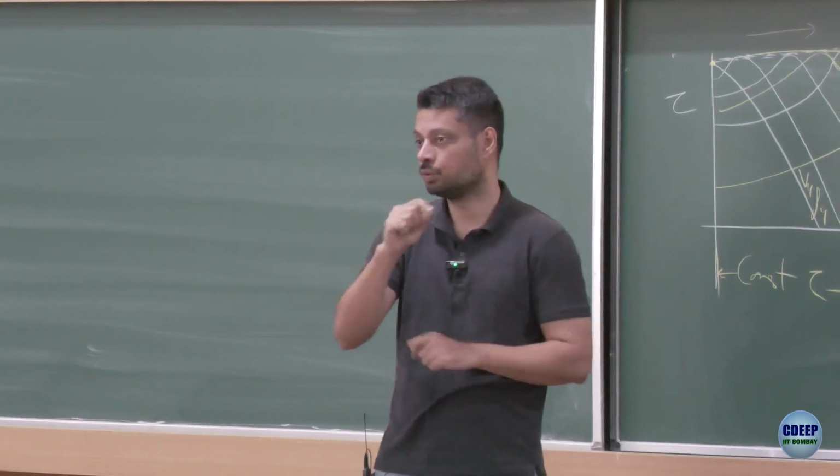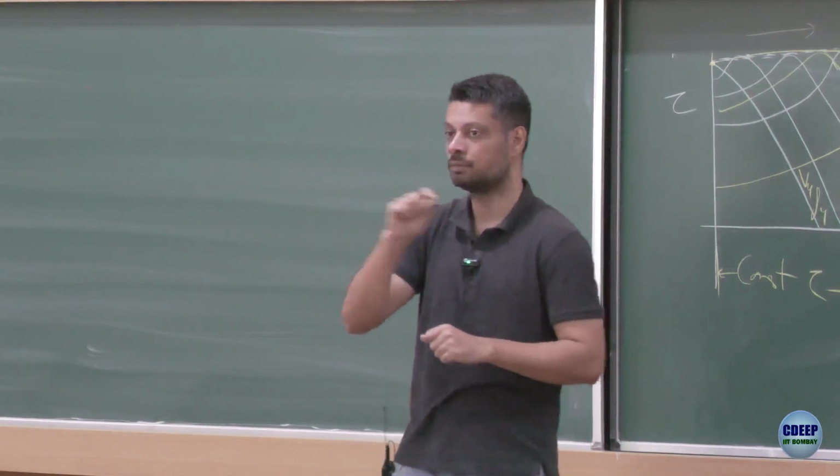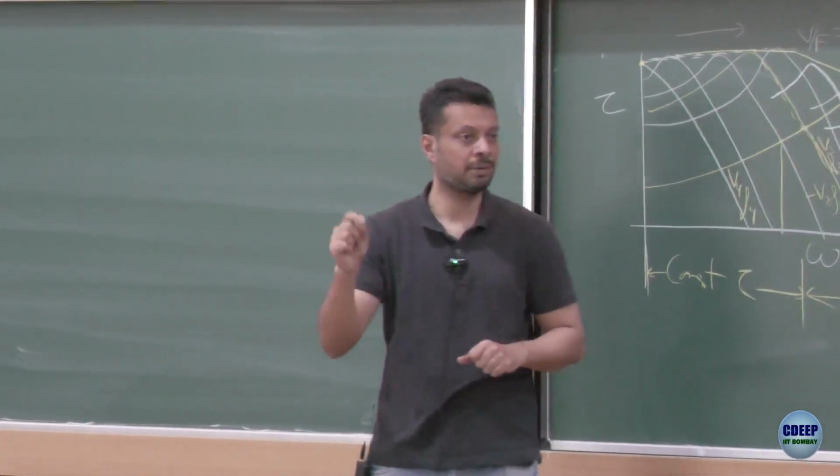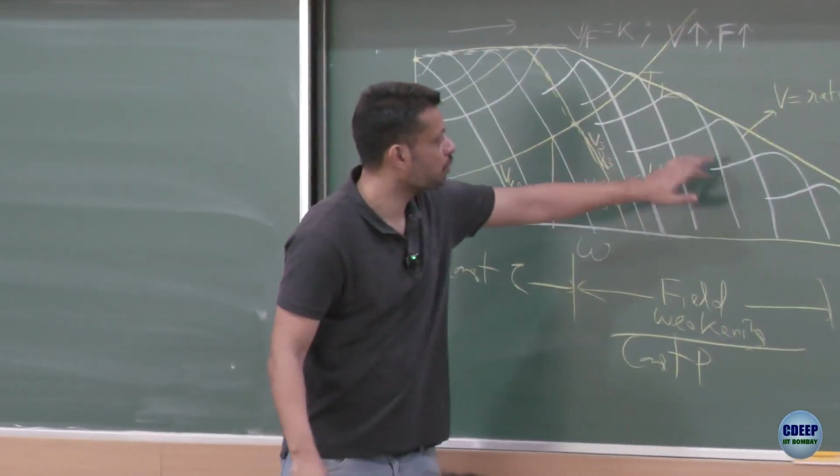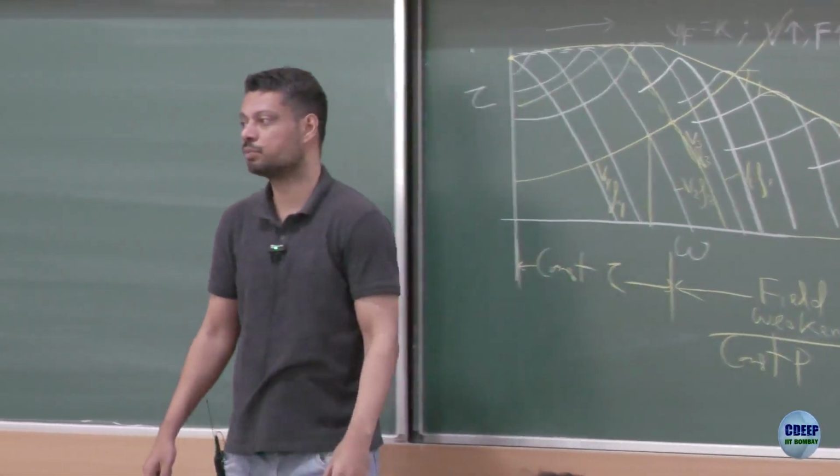Till 50 hertz it would do V by F, and after 50 to 60 it would maintain the voltage and just increase the frequency. So you can get at least 1 or 2 more steps, maybe not too much, but a few more steps.